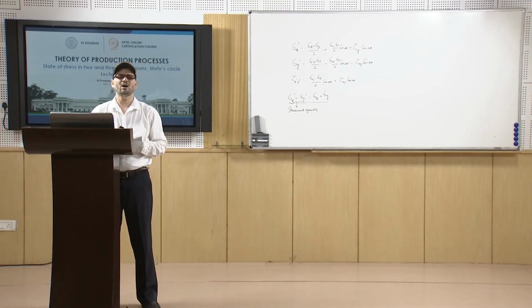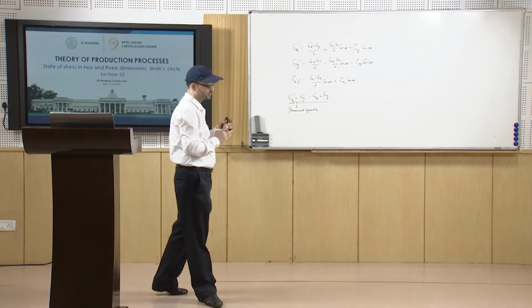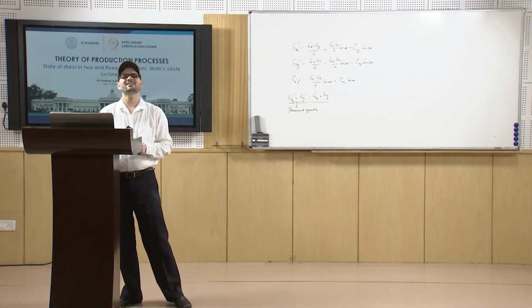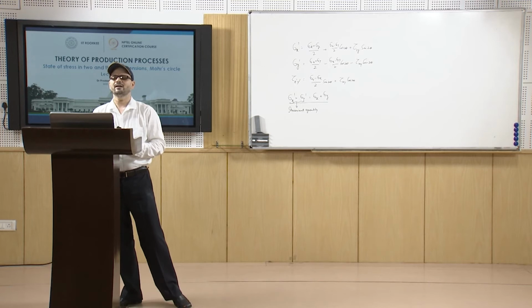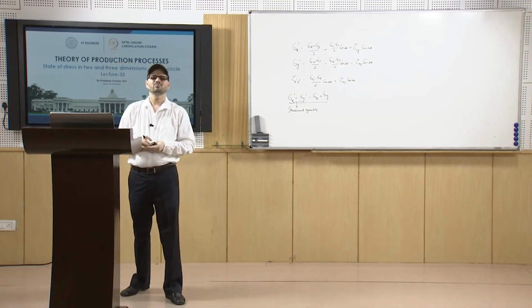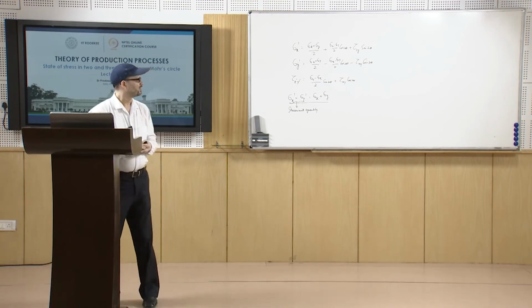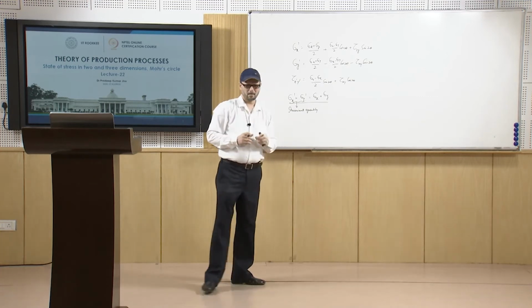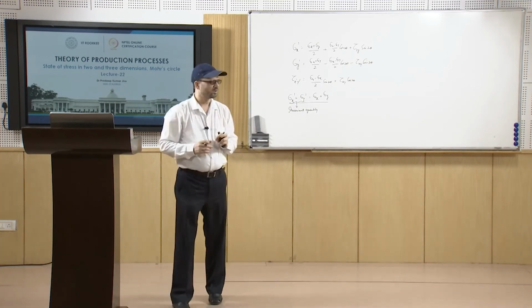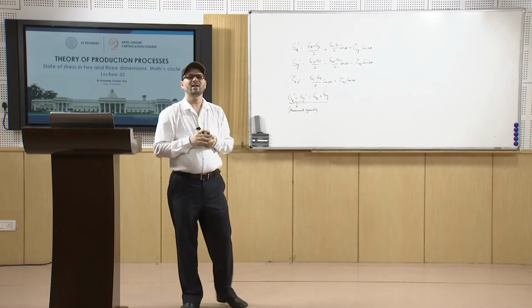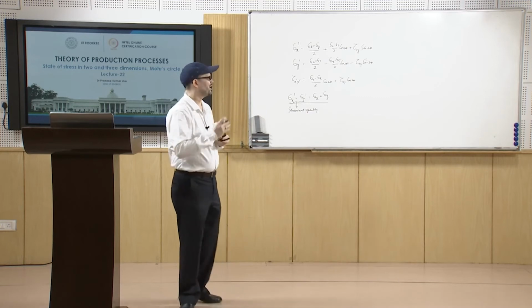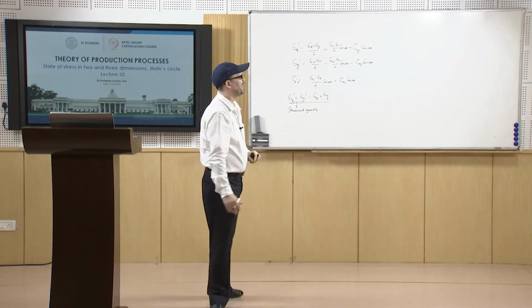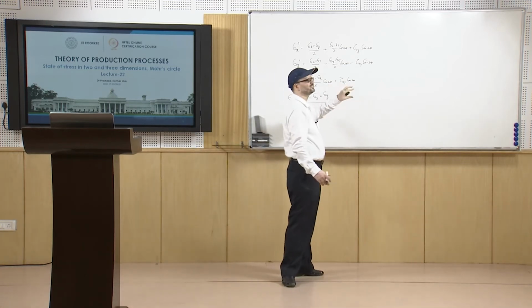This is how, if you have the state of stress in 2 dimensions, with any given values of stress, then for any plane at a certain angle of orientation you can calculate the normal and shear stresses. Now, we call some planes principal planes. The principal planes are the ones where there is no shear stress, and only the normal stresses, the principal stresses, are acting on them.